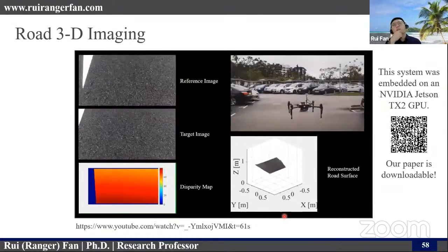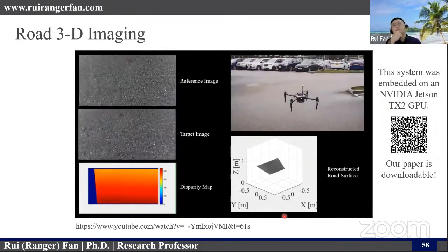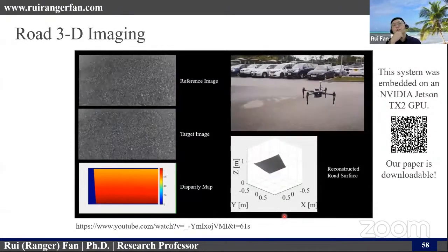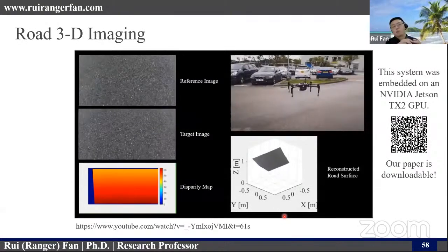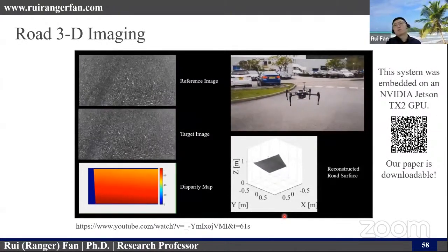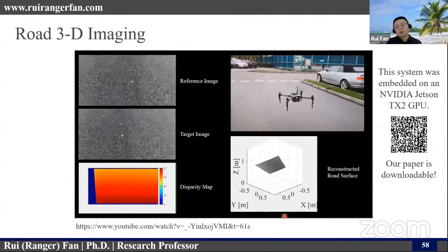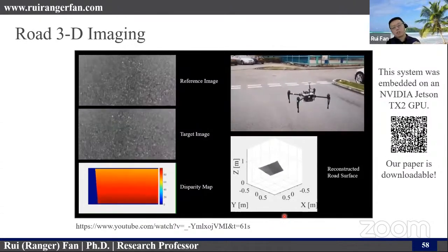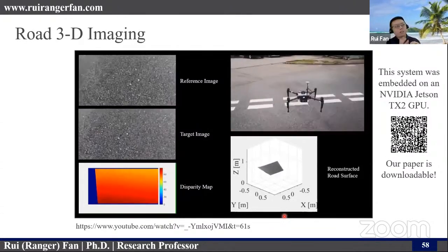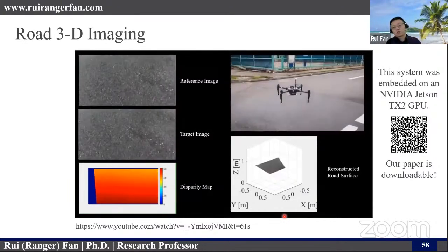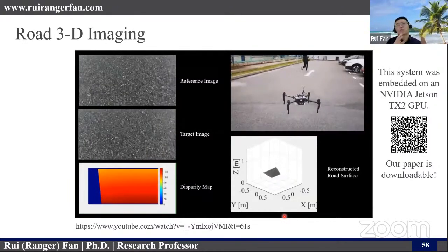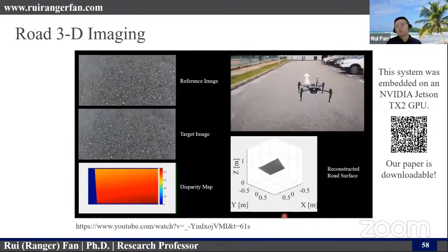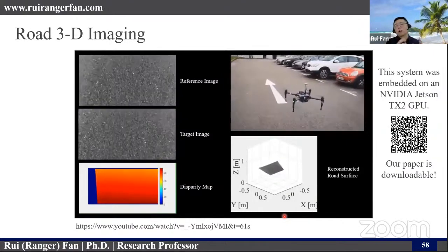In my opinion, I think the angle will not make much difference. If we just install the camera on the car, I think the results will be very similar. But typically, we mount the camera as close to the ground as possible, because we want to capture most of the view of the ground. We do not want to capture other vehicles or pedestrians.